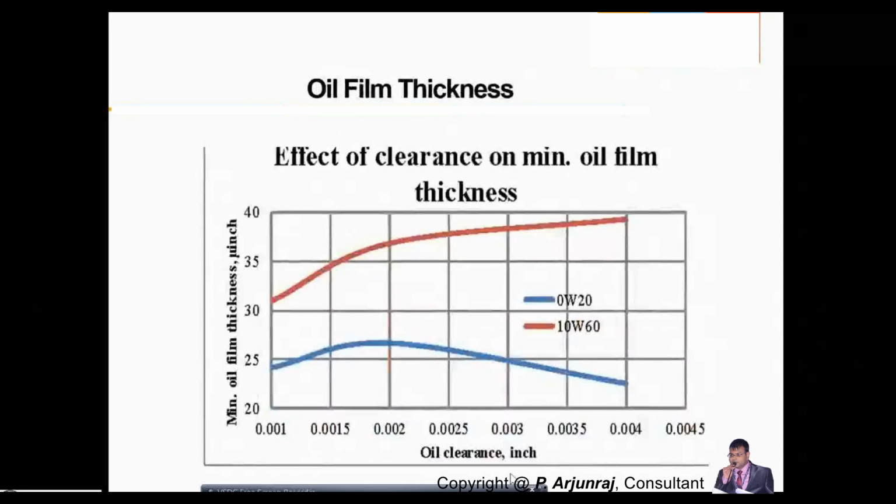See, it is always necessary to maintain some thickness. It is not that the oil should be very thin. It should maintain some thickness, and here the thickness is good, but it should not be too high either. You see in the graph, 0W20 and 10W30 at the ends, and 5W20 and 5W30 come in between. I was telling that the thickness needs to be at a minimum; it should not be too high or too low.